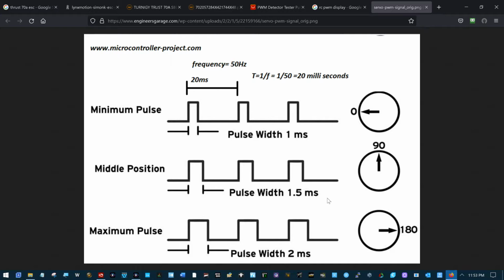So this is the pulse width we're talking about, and that pulse width can vary widely. This will affect how far a servo turns, but the biggest thing it's affecting for what we're talking about right now is how many RPMs you're going to get out of your motor on an electrical speed controller that uses a pulse width modulated signal that goes from low RPMs to high RPMs.